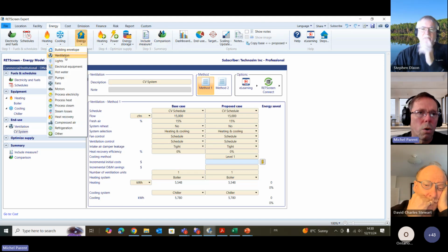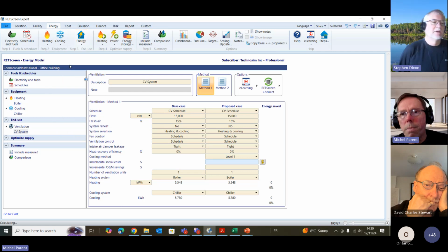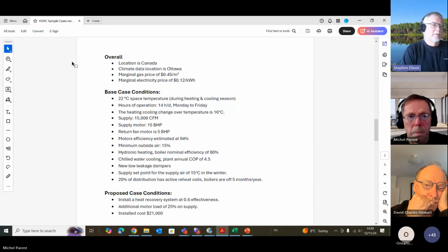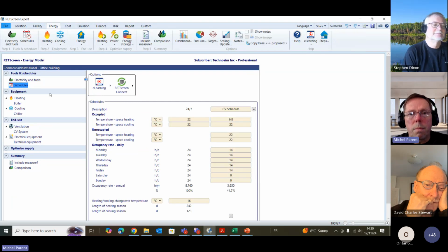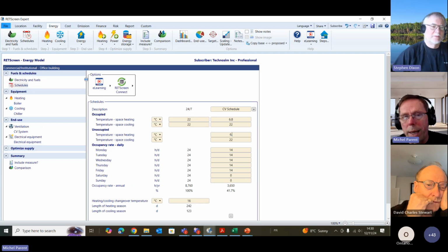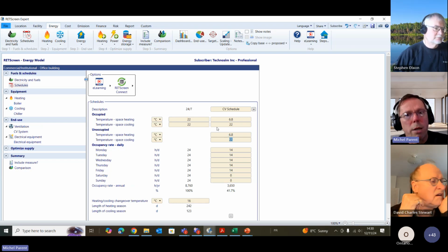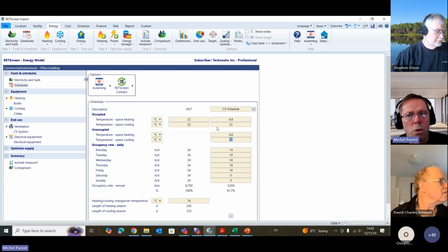So with Michelle, there was a question. Yep. Go ahead. There was a question about the unoccupied space temperature. Do we set that to 6.8 or leave it at the 22? Oh, the system is going to stay off, but you know what? Very good point. Yeah. Just to be safe, and thank you very much. That's an excellent question. It should be 6.8. Yeah. Just in case you forget to put the schedule and you leave constant, at least it will not give you an overestimation of your energy impact.